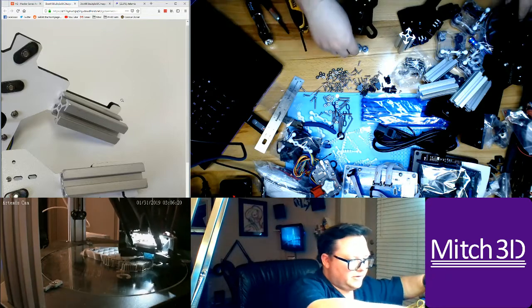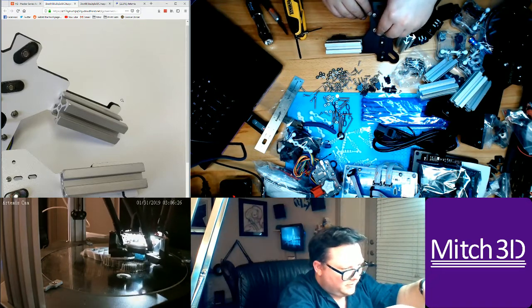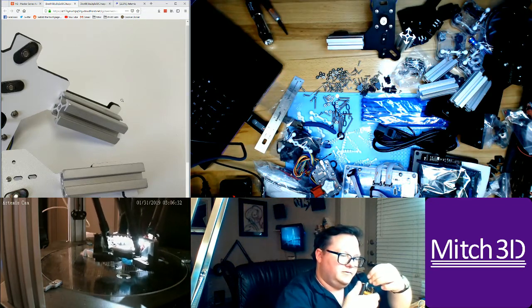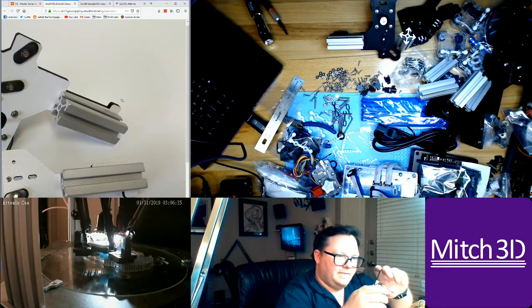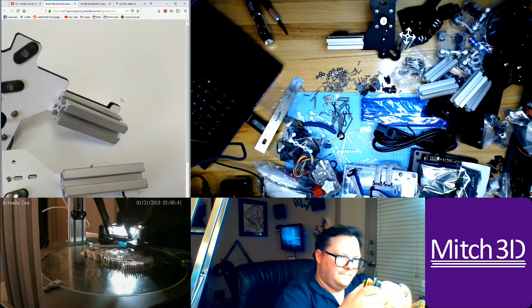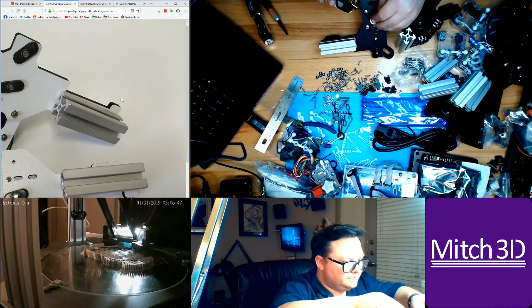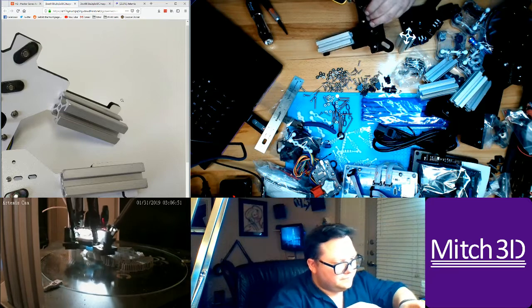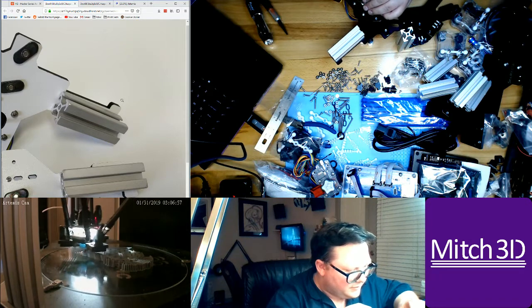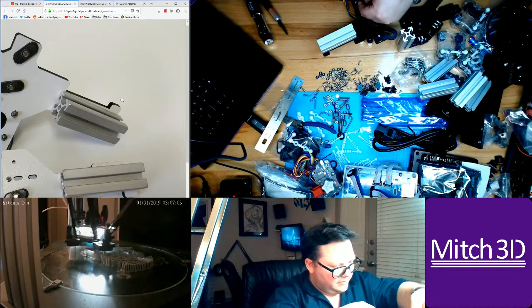Oh, don't forget the motor pulley. That's easy. Just put this here, flush with that. It has a flat, so flush and tighten.